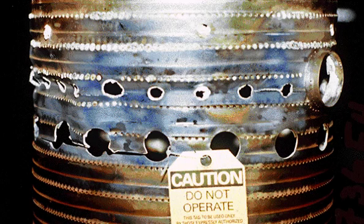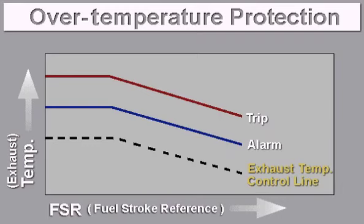Over-temperature protection protects the gas turbine from damage caused by overfiring. Under normal operating conditions, the exhaust temperature control system regulates fuel flow when the firing temperature limit is reached. However, if the exhaust temperature and the fuel flow exceed control limits, the over-temperature protection system provides an alarm prior to tripping the gas turbine. If the temperature should still increase, the gas turbine is tripped.